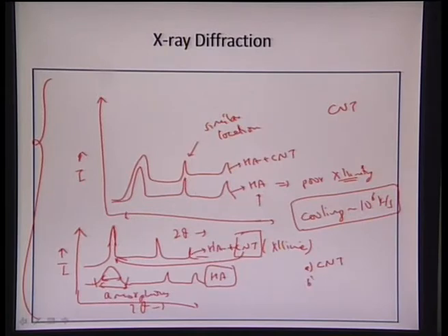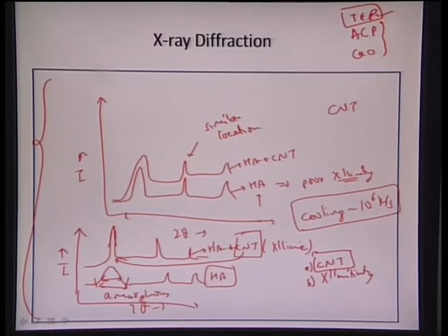And secondly, the CNT peaks are not really being observed out here, and the crystallinity part is also being dominated by the carbon nanotube content. As we see, the processing can also induce some different peaks, which can be tricalcium phosphate, amorphous calcium phosphate, or even calcium oxide. But what we are seeing in this particular spectrum is no presence of any other secondary peaks. But there can also be certain TCP peaks because of the rapid kinetics involved in plasma spraying. So we can also observe some TCP peaks that will induce certain amorphous nature in the particular coatings.